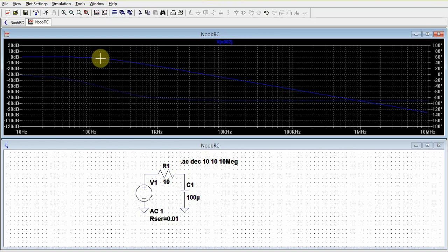And then the greater the frequency after this point, the weaker the signal gets across C1. So basically, you could connect something else in this path here, and that would effectively not receive these higher frequencies, or would receive them at a very low level compared to this.